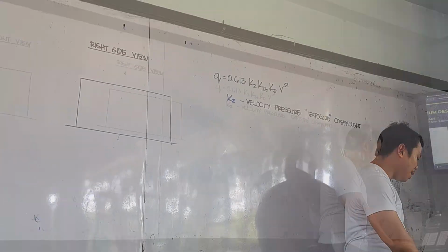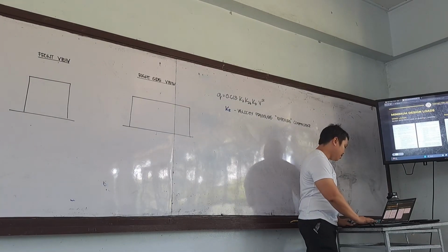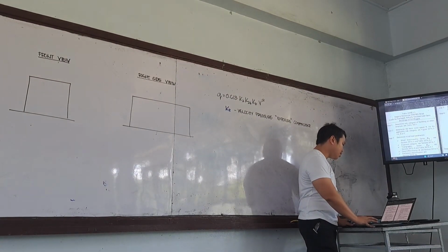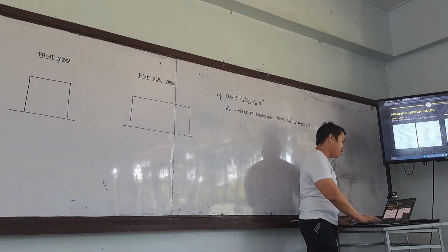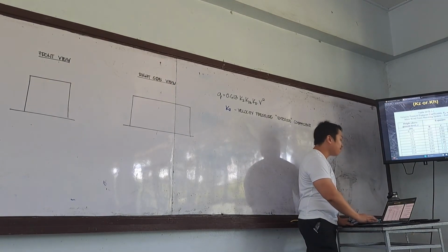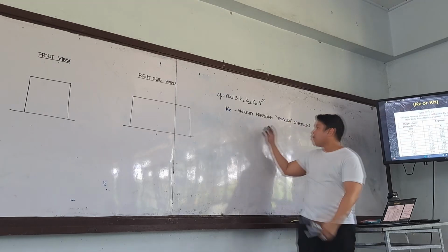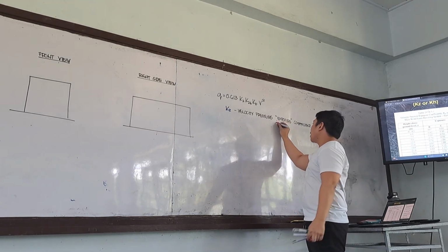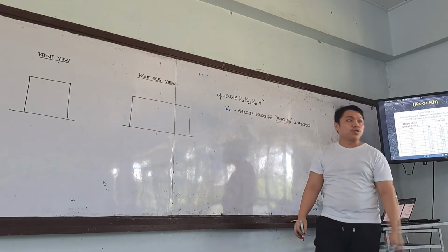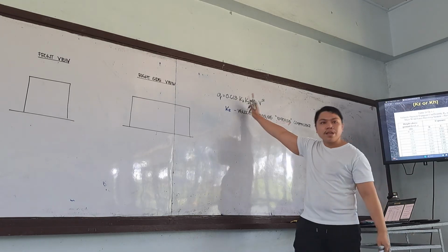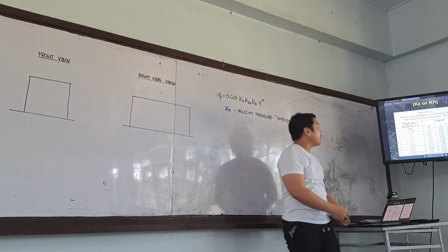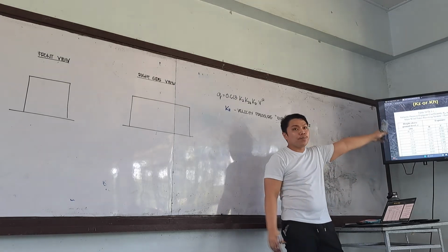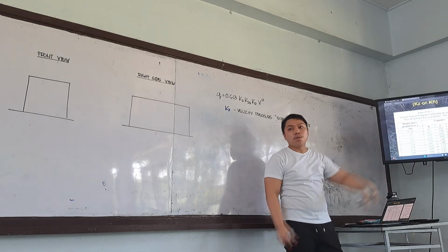Under our steps, what is the first? First, identify the exposure. There we will start from our last formula. For our basic, again, from the name itself, it is based on the exposure. The keyword is basic, based on exposure. So we'll have 3 types of exposure: exposure B, exposure C, and exposure D.